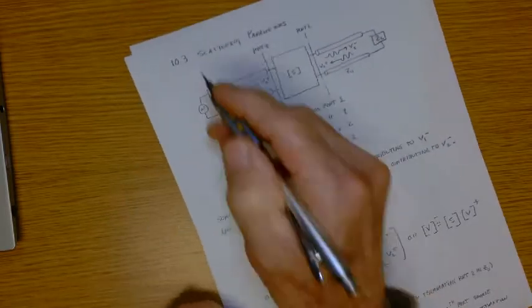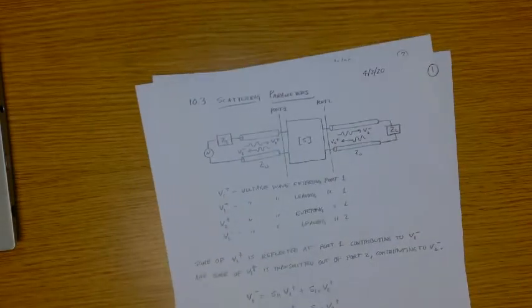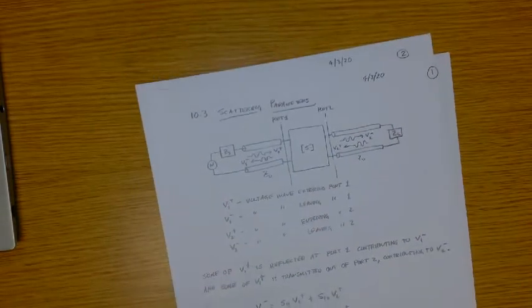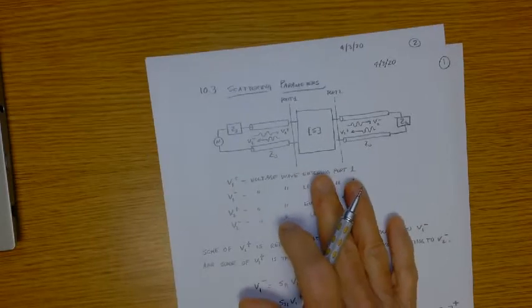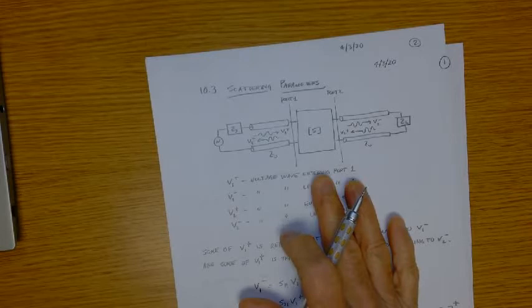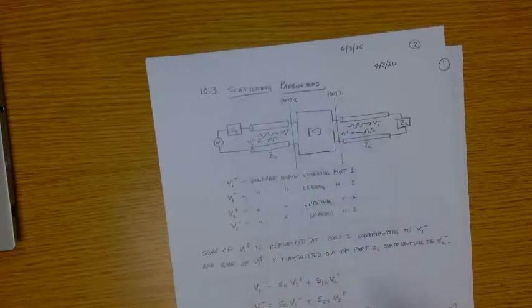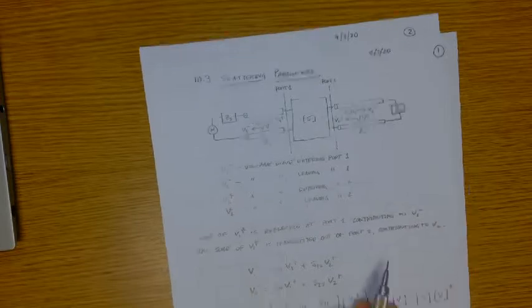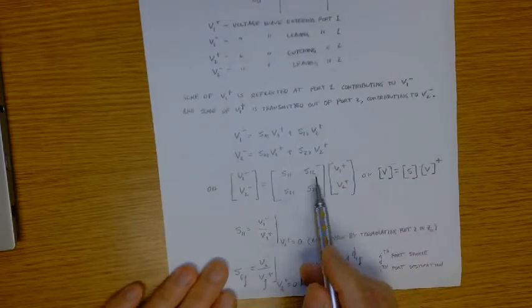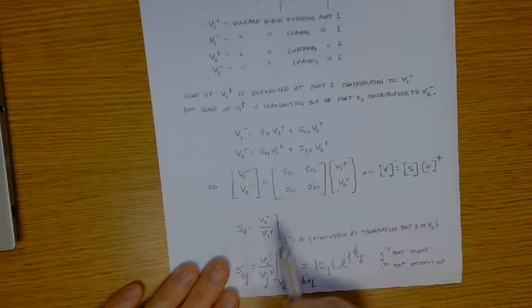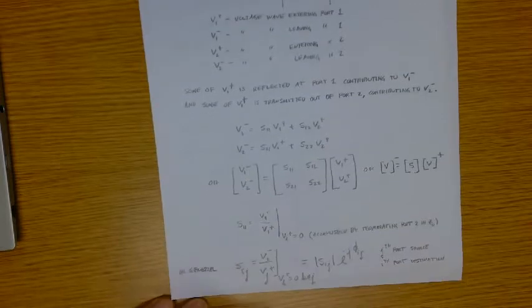Okay, so scattering parameters, right? Scattering parameters are important because that's how we describe microwave networks. And we'll mention in a minute, toward the end of the presentation, that the network analyzer represents a microwave network in terms of scattering parameters. So the network analyzer will actually measure S11, S12, S21, and S22 over a range of frequencies, right?